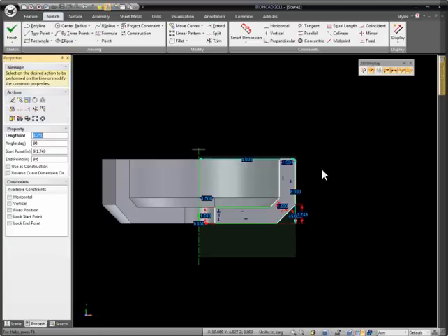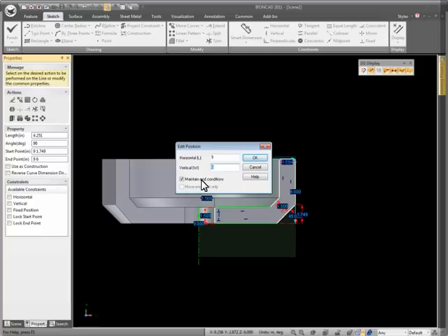When you're on some of these elements, when you right click on them and you hit edit, you notice there's options here for maintaining end conditions. As you notice, when I spoke earlier, when you edit some of this geometry, it maintained the perpendicular angles and such. You can uncheck these options when you bring up the dialog boxes to give that same behavior of holding the shift key down when you drag, where the lines can adjust freely depending on what they want. And that's useful for conditions like this. You know, if you wanted to adjust this length and maintain this angle, you know, that's what this option is on, and that's why it's on by default.